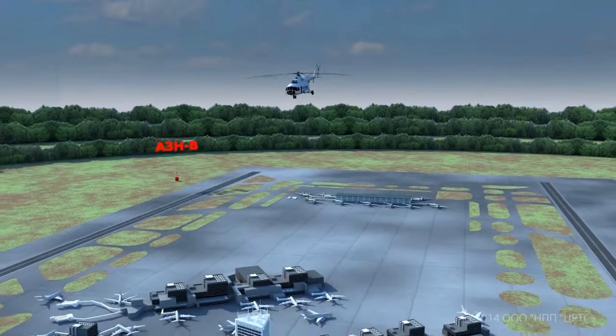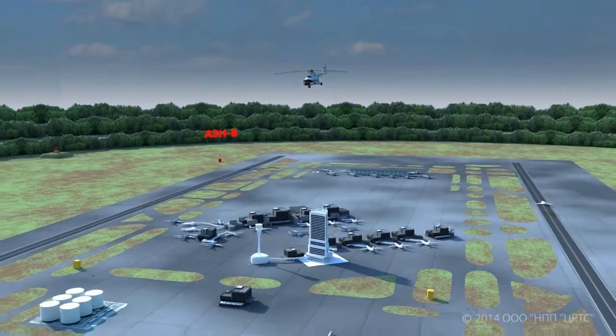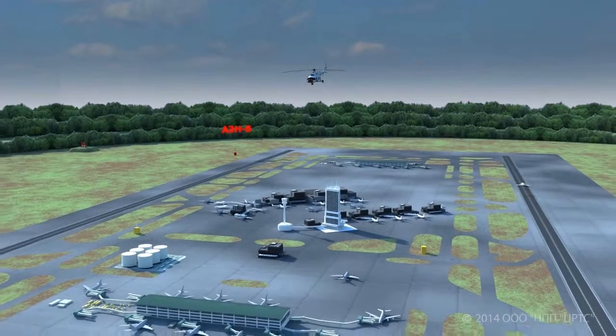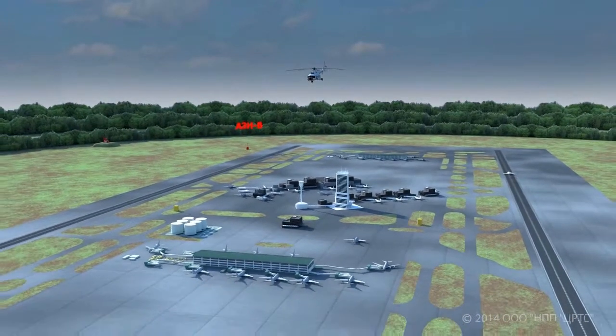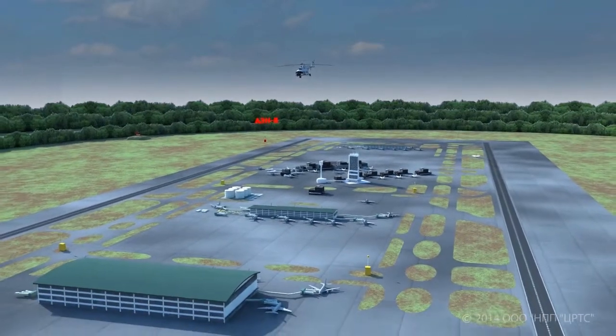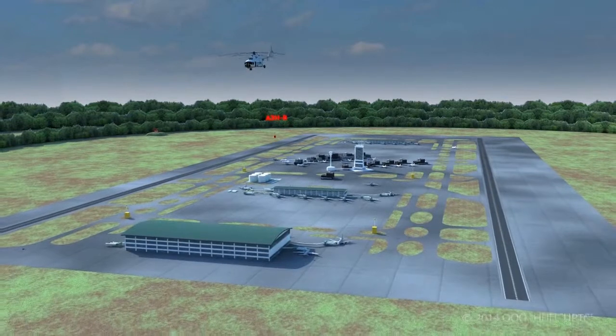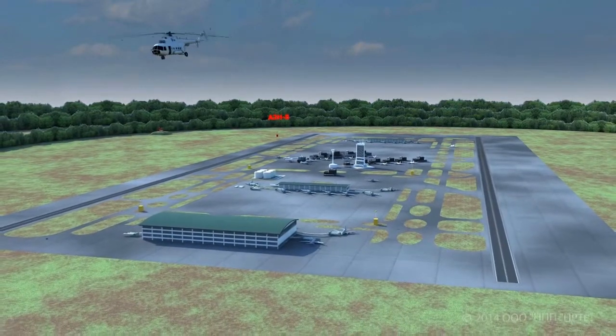This technology is based on the principle that the aircraft independently determines its coordinates by signals of global navigation satellite systems and transmits them on the air. A ground ADS-B station is very compact, which simplifies its placement and allows the use of the infrastructure of mobile operators.